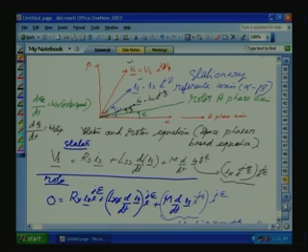Okay. Now, let us go to the rotor. Applied voltage is equal to 0. But due to the rotor current, that is IR underscore, we will have a voltage equation Rr into IR underscore here.